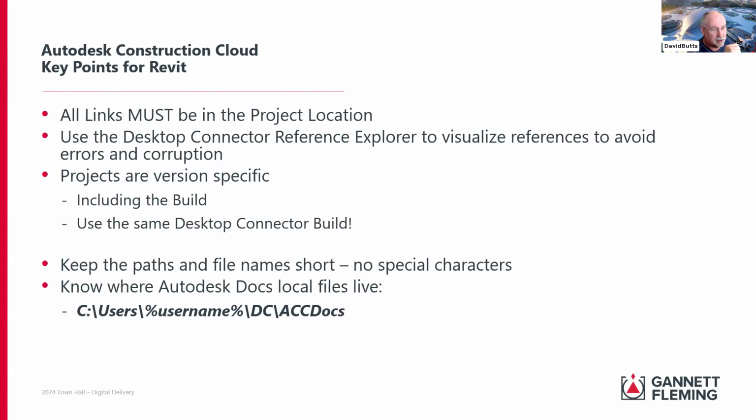Actually, it was really funny. I saw somebody from Autodesk that I'm not going to mention that actually had a % sign in the file name and in the path of a file that we were working on that we were testing for development. And I'm saying, you realize that that's going to wind up corrupting that file because the OneDrive APIs in the Windows environment, they have restrictions on what you can use in terms of special characters. Here's a great idea. Don't use them. How many of you know that a space in a file name or path actually takes up 3 characters?